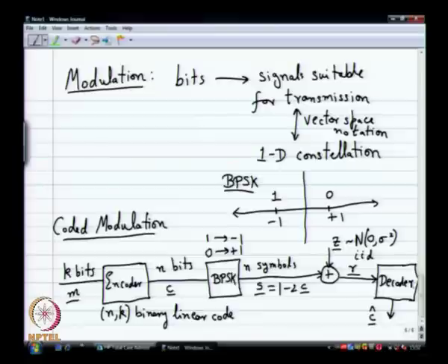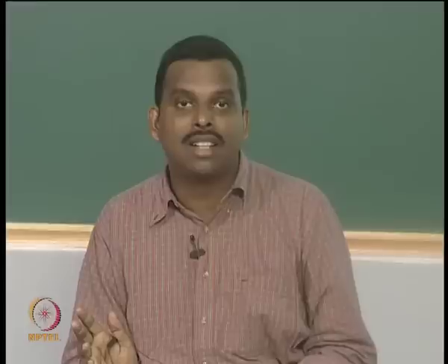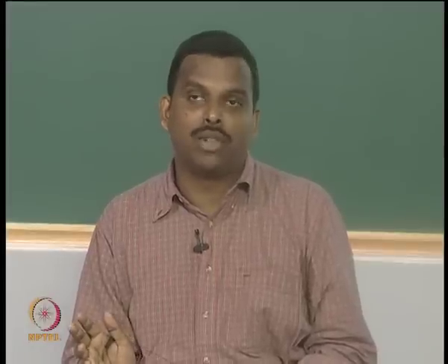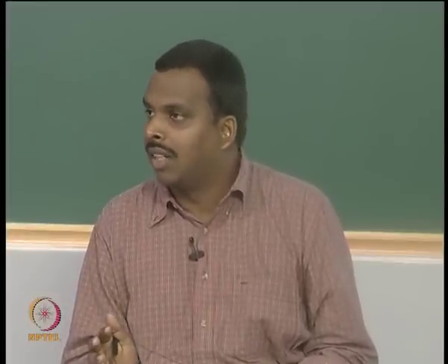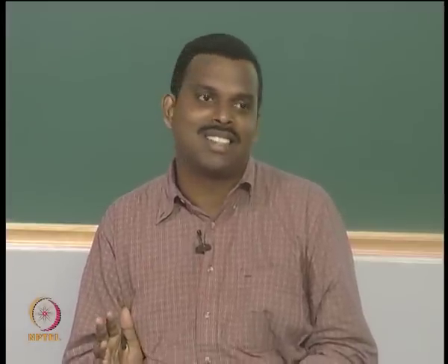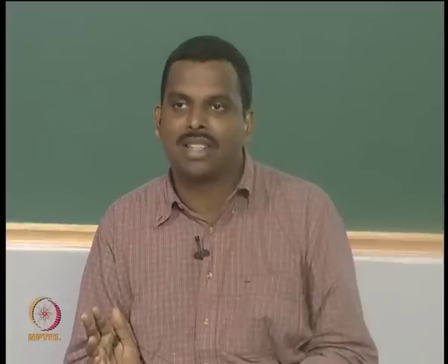Is that okay? So, this is a big difference. Hopefully you agree with me that this is very different from the decoders that we have been seeing so far. These decoders we have been seeing so far work in some Galois field, for the Reed-Solomon code. If you are using a Reed-Solomon code here, they work in a Galois field, not in the real field. It makes no sense to use them on the real field. There is no direct way, you can't compute a syndrome, it would not make any sense, there are no roots, no polynomials, nothing.